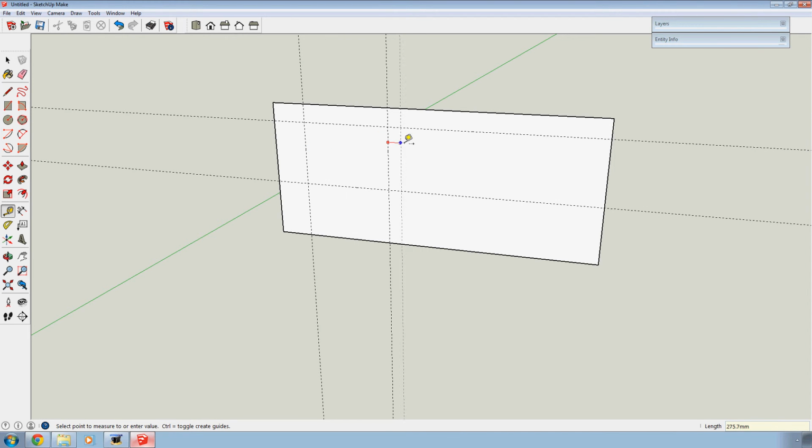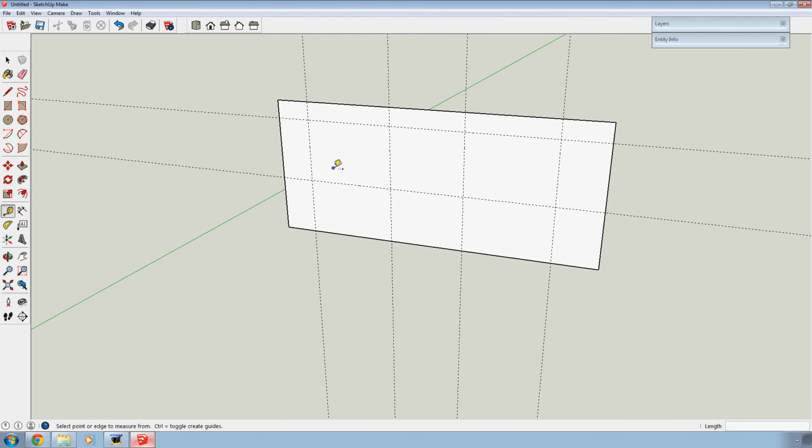Now there's a gap of 1250 to the next window. This one is 1465 as well. And I'm just going to check this distance, 735. I've actually got 740 on the drawing, but 735 will do very well. If you do have a discrepancy, as you often will, between your measurements and the SketchUp drawing, always draw the dimension a little bit smaller.